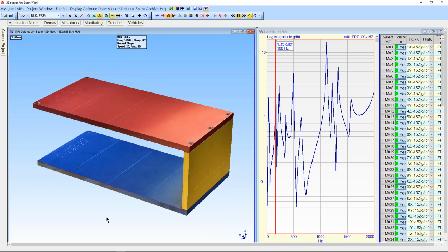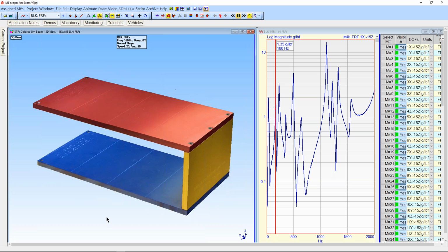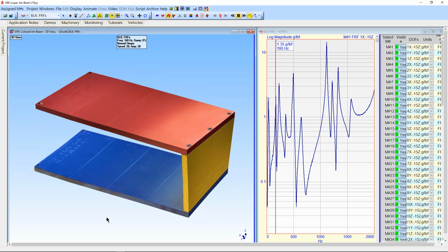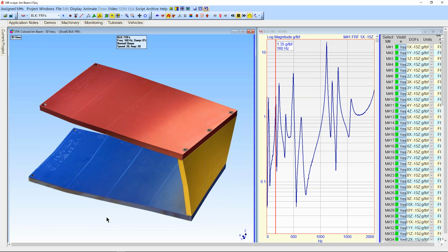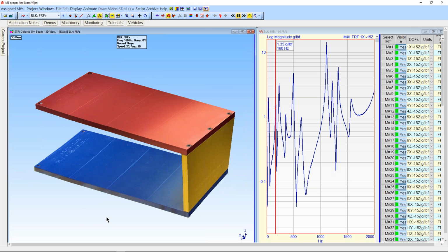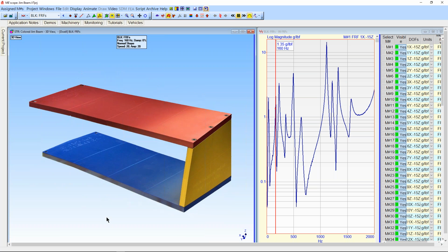Modes of vibration are a manifestation of energy that's trapped within the boundaries of the structure, in this case, the aluminum plates. There's a discontinuity between the aluminum material properties and the surrounding air. So when a structure like this is excited by forces, in this case it was impacted with an instrumented hammer, the vibration was measured in the form of a set of frequency response functions.